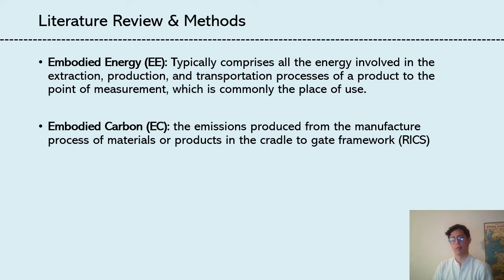Just to get to the point of what is what, we understand embodied energy as all the energy involved in the extraction, production, and transportation of a material, and embodied carbon with a similar definition, that is all the carbon emissions produced by that extraction, production, and transportation of a material. We use the framework and guidelines of the Royal Institution of Chartered Surveyors because they have wide information about this, and we use this to guide our research.